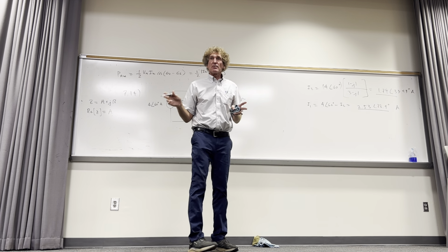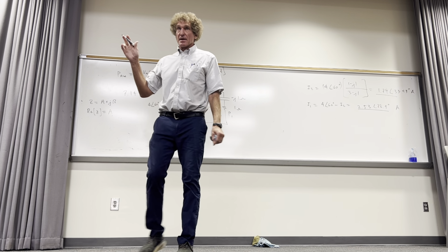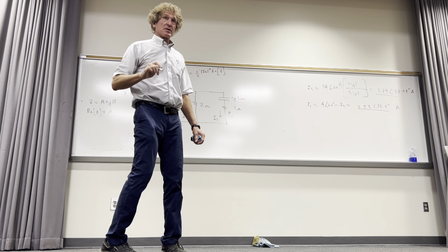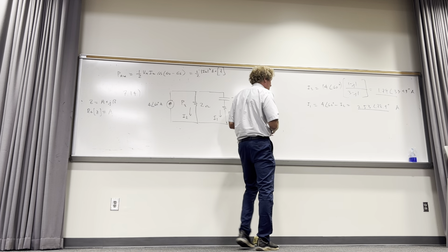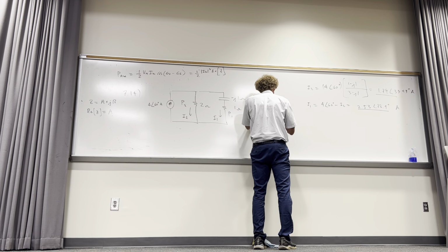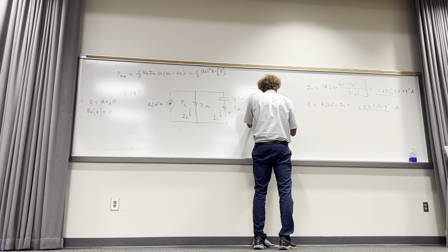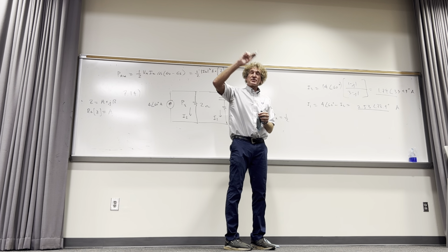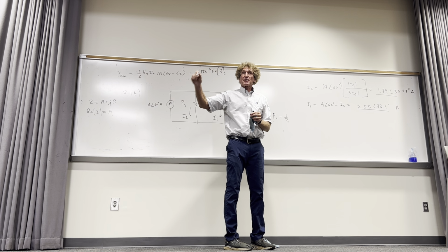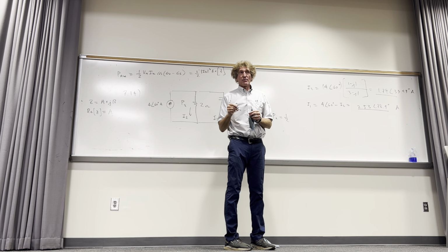Now, do we agree those are the currents? Let's try that. Okay? If they are the currents, then what is the power associated with this 2 ohm, or dissipated by this 2 ohm? I'm just calling it P2. Well, it would be 1/2 because these are peak values of current. You all with me? If a cosine waveform was used to describe that current, it would have a peak value of these current magnitudes. Do you all follow me on this?